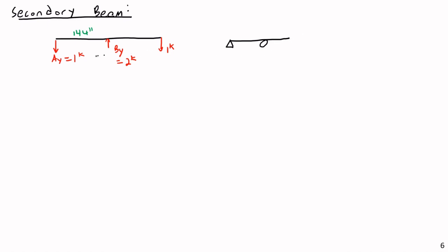Instead, I'm actually going to have to go about this a long way and find the load, the shear, the moment, the rotation and deflection for the first span, and then use the endpoint of that as the boundary conditions for the left end of this span. So let's go ahead and do that. I'm going to analyze the first span first. So analyze the left span. And by analyze, I mean find the shear, moment, rotation, and deflection functions. So let's go ahead and work through this.